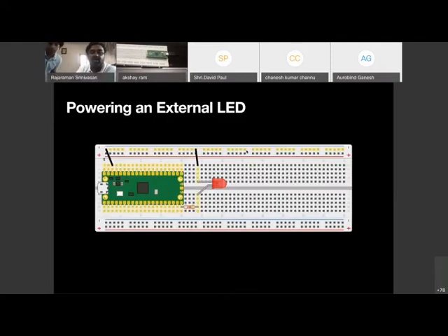Okay. So for this external LED, there is an associated code. So the first is the hardware setup, right? So that we completed. So let me repeat it quickly. You are going to take this line number 24 here. You are going to take a jumper cable and connect it to the earth, the ground side here.